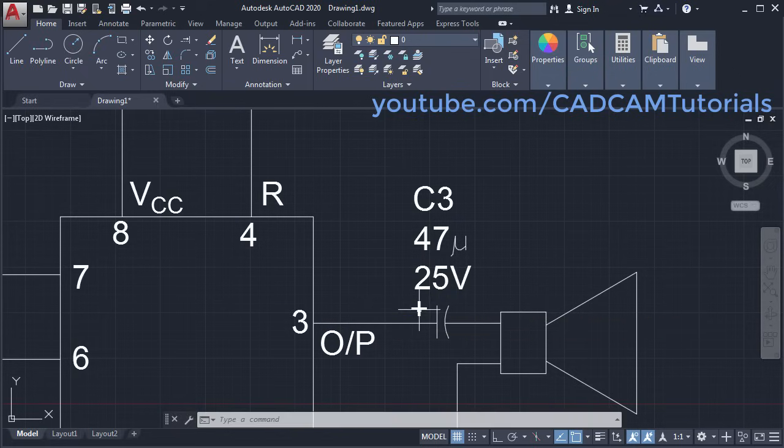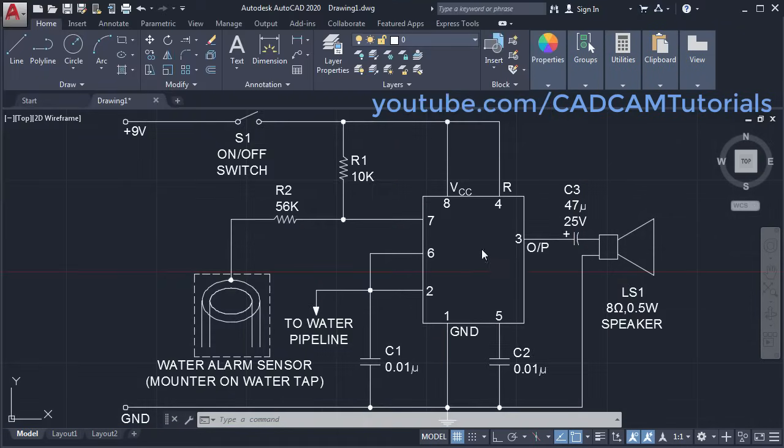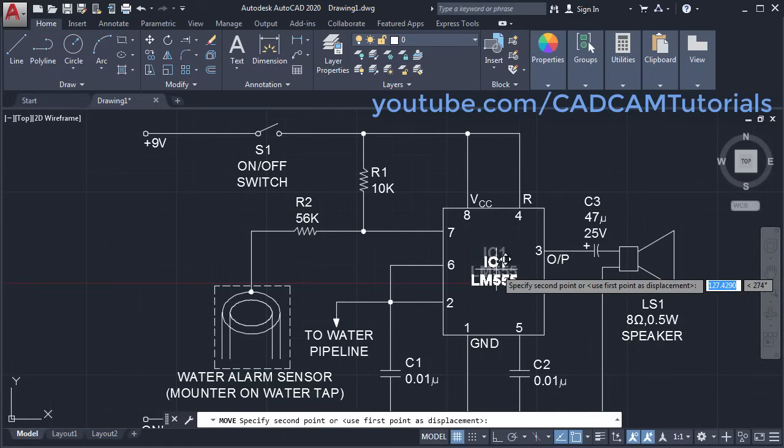Okay, one more text is there, this IC1 LM555. Copy this one, enter, base point, click inside, enter, double click and select it, make it center align, make it bold and increase size 150, enter, click outside, then move it, enter, select object, enter, base point and place it in the center.